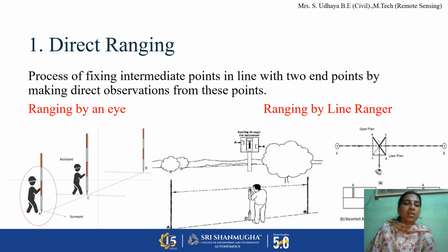He can tell them to adjust the position of the rod so that ACB makes a straight line. This is ranging by eye.